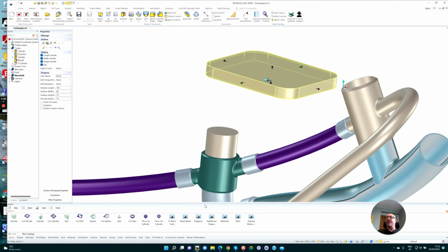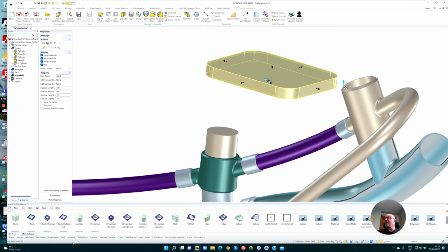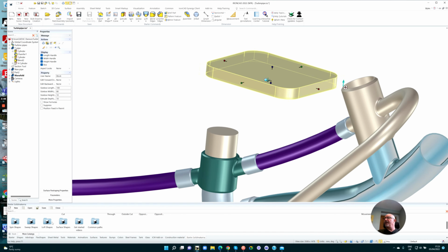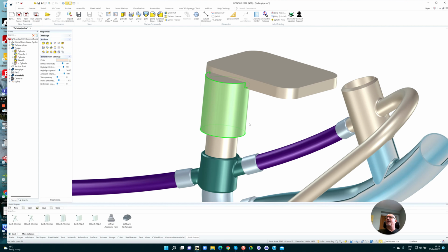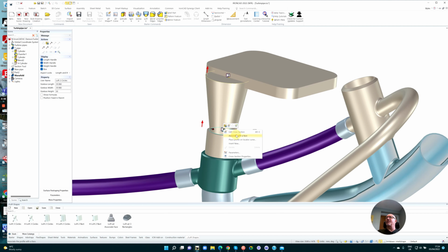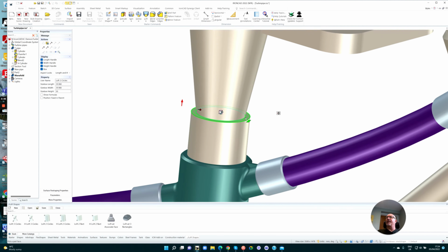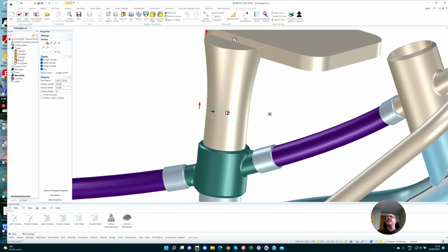a loft shape. So I'll go to another catalogue that I've got, and I'm clicking my loft shapes, and I've got a 2 loft circle. I just drop that onto there, and I'll open the loft shape up and change the diameter a bit to there. And then I'm going to say I want to associate to a face, and I zoom in, make sure I get the right face. I want to associate it to that. It's got a tangent factor of say 20. That should be okay. And then we'll do that loft there.